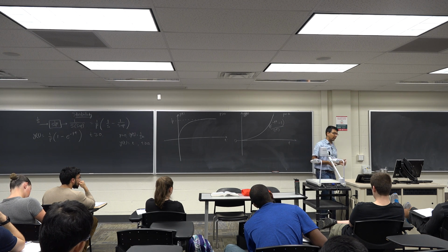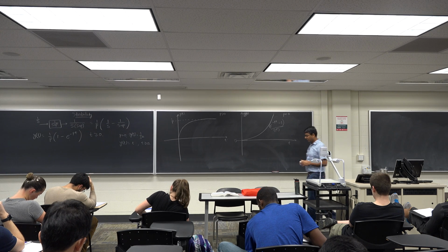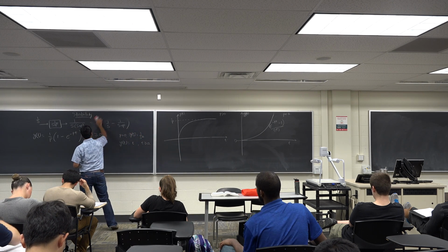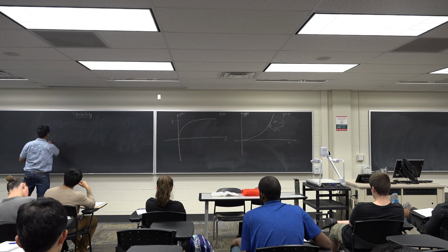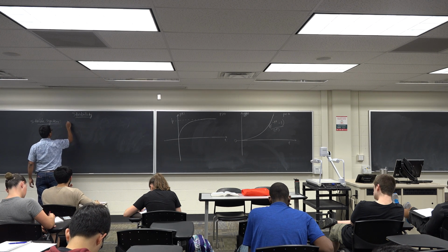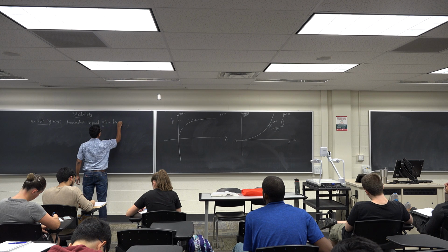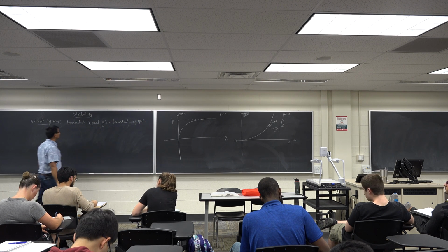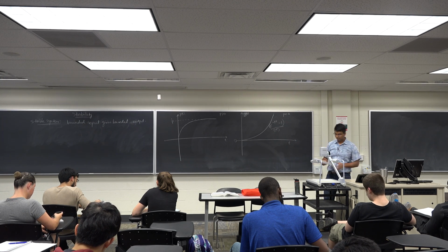Marginally stable means that you give it a bounded input, you get a bounded output, but the output doesn't really converge to something. It just oscillates. So we have three concepts of stability. Well, not three concepts. There's just one concept, and then a refinement called relative stability. So that's what we want to talk about. A stable system is the one that gives bounded output for every bounded input.